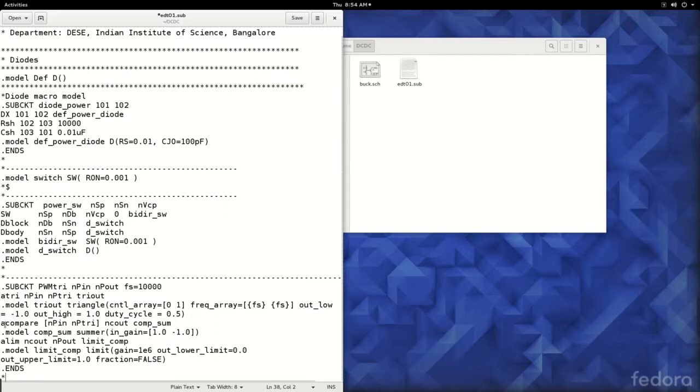I have used A as a prefix for these lines here to indicate that they are analog behavioral modeling. Not necessary that you should use A, but it is a good practice. Now it has three major parts, which I will show by going to the notepad.